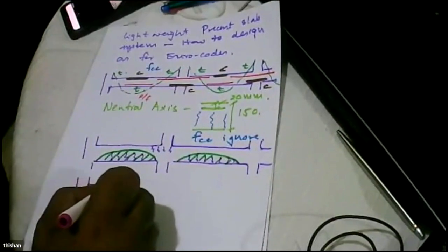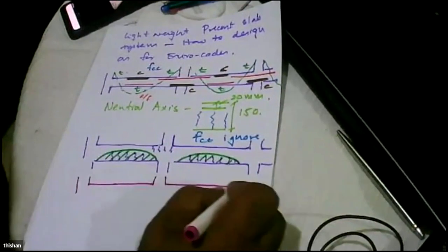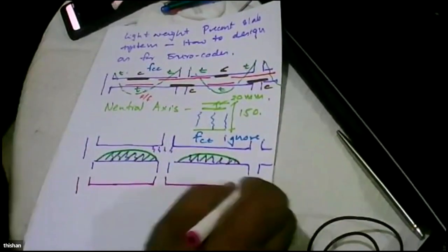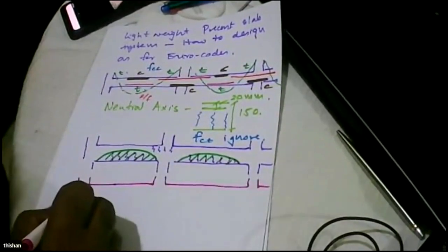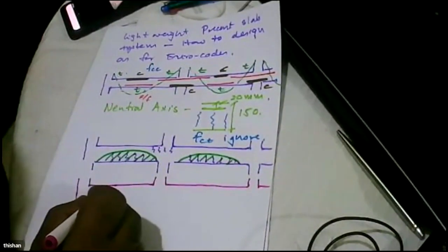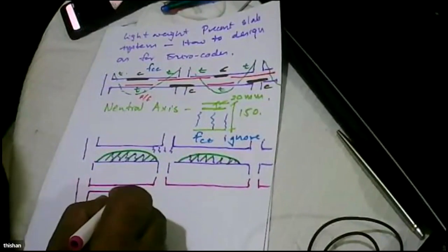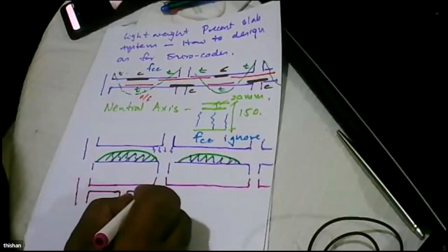Now we are going to have a slab. The top surface is intact, but that's the important surface for us. This surface, let's make it thin. But if it's thin, it's going to sag. So put a beam.